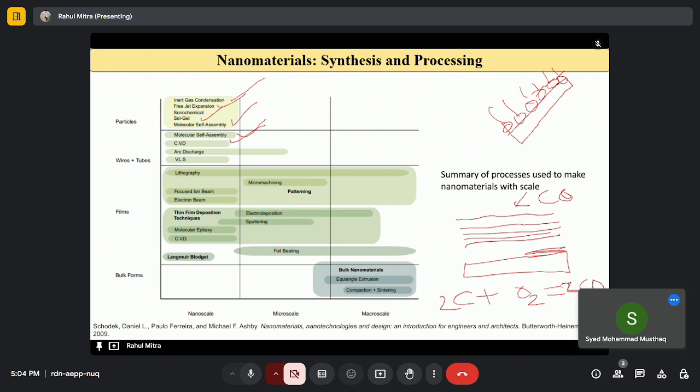This is the gasification reaction. We need to maintain the temperature below the equilibrium temperature. Then this reaction will go backwards, and this 2CO will dissociate into carbon and oxygen. So if we have a substrate here, for example copper or silver, due to the lower temperature the reverse gasification will happen.